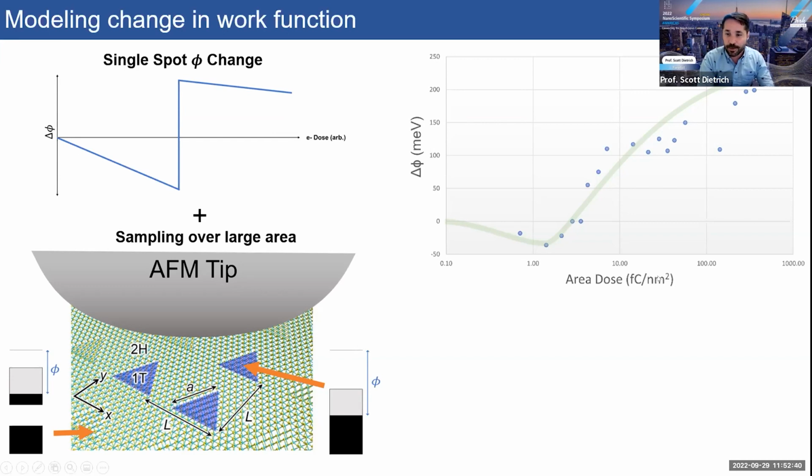But for example, to write a 1 micron squared area here for the higher doses, just for one of these squares can take about 30 minutes. It's just a lot of time in the E-beam system. So unless we're doing overnight writes, going to another order of magnitude quickly goes from 30 minutes to several hours, just for a 1 micron squared area. So writing large area is inefficient, which is a well known throughput issue for E-beam lithography.